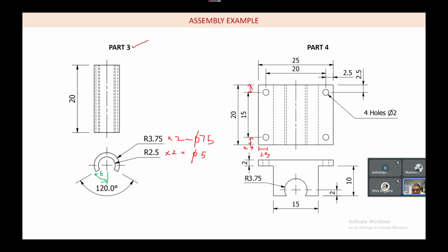So again I have to insert 3 more sleeves now. One sleeve, one by one we will do. Constraint, axis, this is now okay. So now flush, apply.